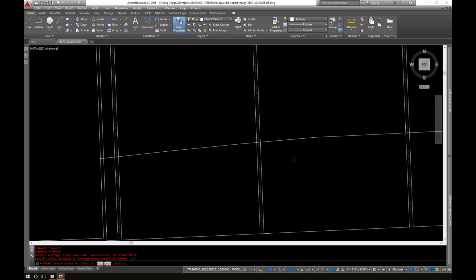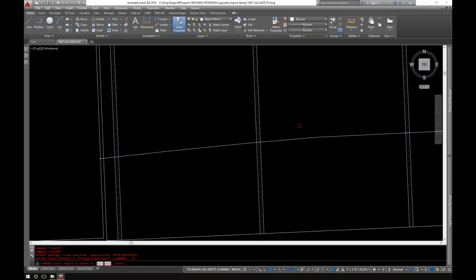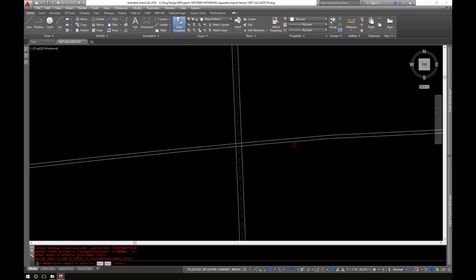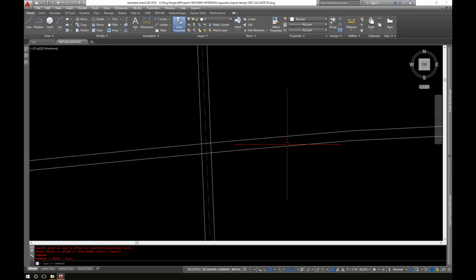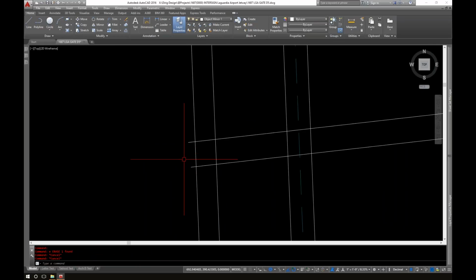And the railing was about 1.5 inches diameter. This is just a guess. So I'm going to offset 3/4 both ways. So this way, and then I'm going to delete that guy. And now this was a bullnose type situation. So fillet radius. And I just picked one way. And this needs to not be connected. Fillet radius. Oops, fillet radius.